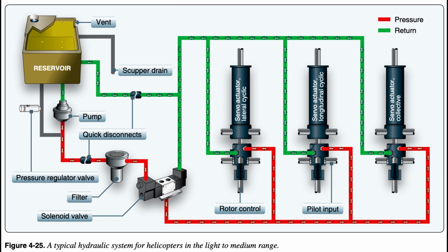In the event of hydraulic system failure, a pilot is still able to control the helicopter, but the control forces are very heavy. In those helicopters in which the control forces are so high that they cannot be moved without hydraulic assistance, 2 or more independent hydraulic systems may be installed. Some helicopters are designed to use their hydraulic accumulators to store hydraulic pressure for an emergency, allowing for uninterrupted use of the controls for a short period of time following a hydraulic pump failure. This gives you enough time to land the helicopter with normal control.